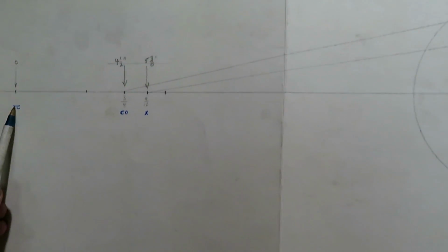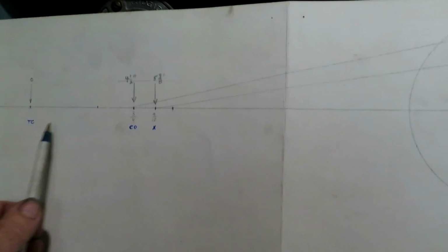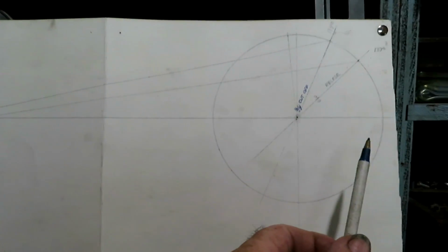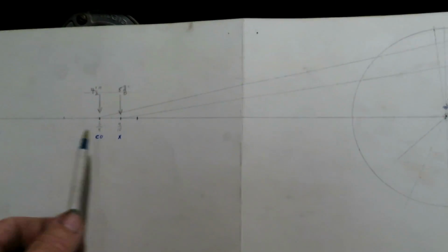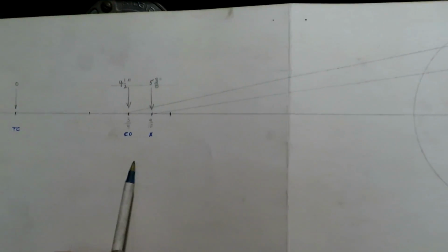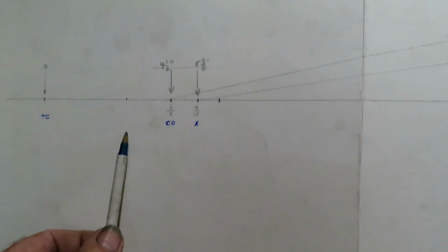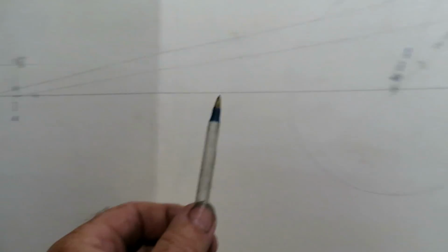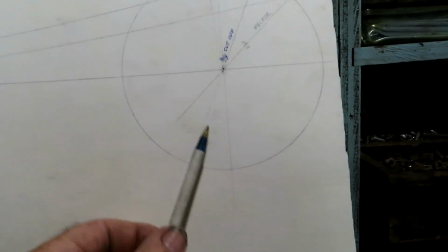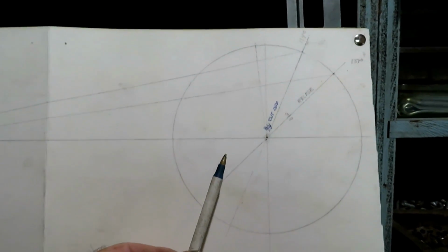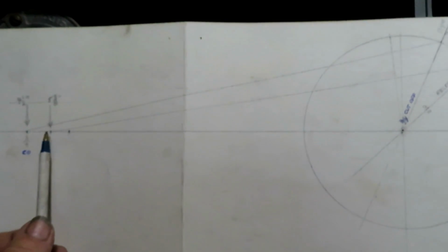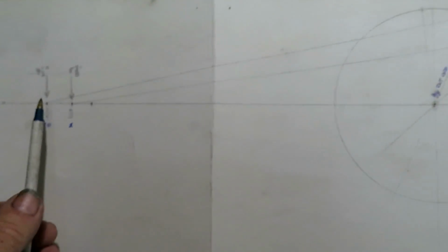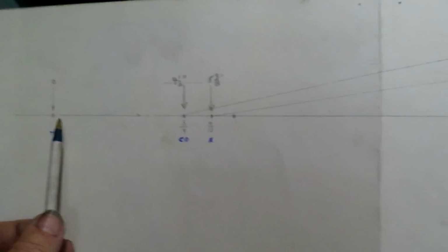What I'm concerned with is that this is the top dead center, this is the bottom dead center. This is laid out in 100% scale. These are the actual sizes of the things that are on the engine. And this, of course, has got a 6-inch stroke, so this circle is 6 inches in diameter. It's got a 15-inch center to center rod. So this line from these points up here is the rod length at 15.